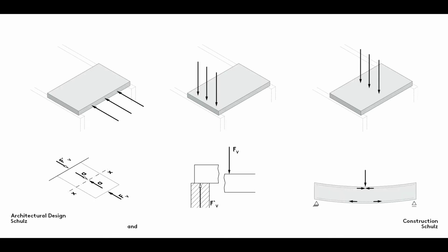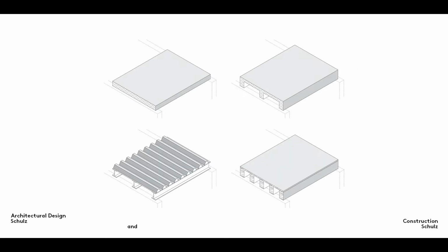constructed. In structural terms, the construction of a flat roof is very similar to the construction of a floor or ceiling. Though the environmental loads are slightly different, the transfer of loads in a flat roof is basically the same as in a floor. Horizontal forces generate longitudinal compression and tension loads, vertical transverse forces cause shear at bearing points, and vertical forces at the span center result in bending forces that in turn create compression and tension forces within the component involved. The various possible types of flat roof construction, depending on the materials used, are therefore the same